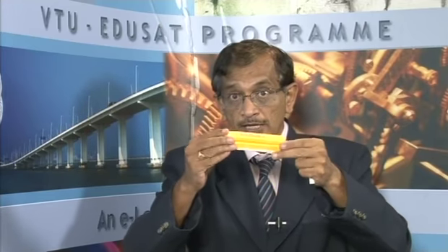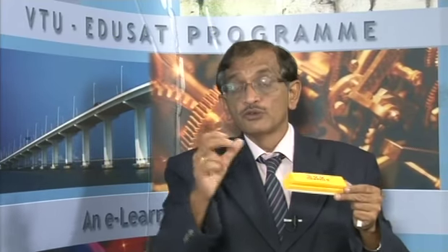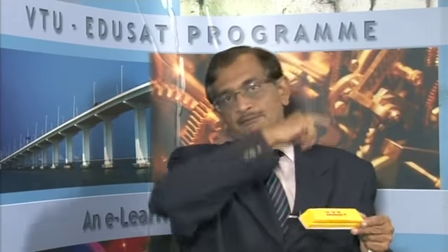It could be a pipeline, a portion of a pipeline, or a piston in a carburetor of an engine, or a submarine, or any fixed body or fixed volume of mass over which we would like to see what is happening, the time history for its pressure, its velocity, its displacement and time. So hopefully I am able to give you the concept. What is the Lagrangian approach? Tracking of some particle. What is the Eulerian approach? Fixed volume approach. Is it okay? Let us go to the next one.